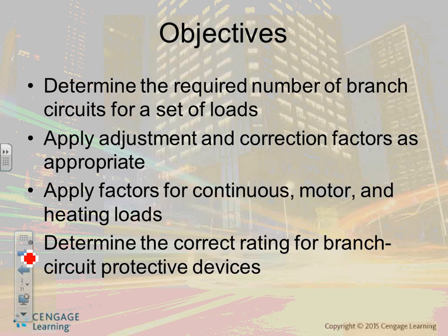So I can use them in terms of wiring methods. I can use this MC cable, not the size, but the type MC cable, as a service conductor, service circuit, or a feeder circuit, or a branch circuit. Does that make sense?